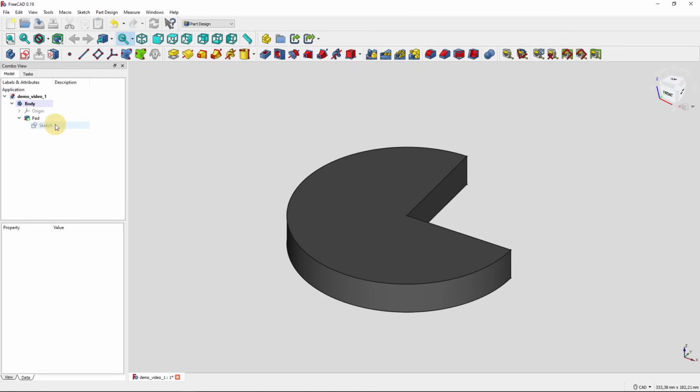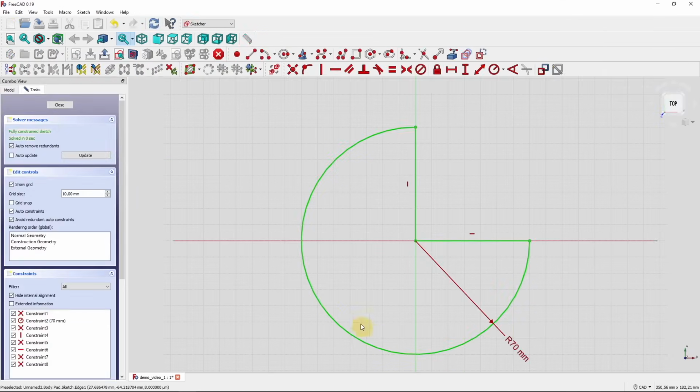The next question that certainly occurs: which method do I prefer? So it's pretty simple. If you want to start your design with a very simple feature, like a box or a cylinder, something that you find here in the primitives menu, it's absolutely fine to start with a primitive. But if you're going to more sophisticated designs and you're not starting with such a simple sketch like this one here, you will certainly want to start with a sketch. And this is going to be the subject of the next video in this basic video series. How do I create professional proper sketches using the Sketcher Workbench?